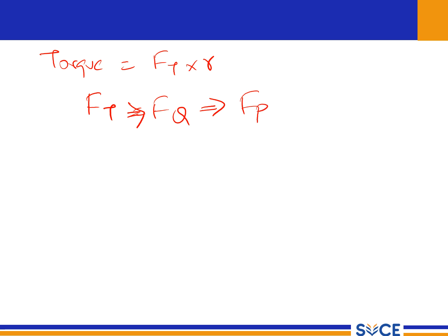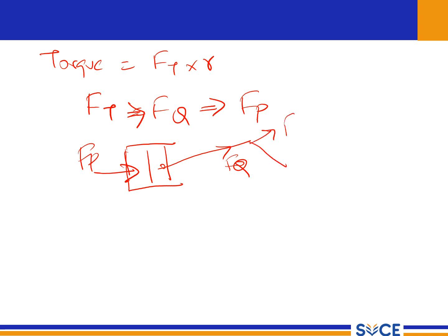That is the reverse order. The net piston effort Fp is transferred to the connecting rod, then to the crank. In order to calculate Fp, we need two forces, FL minus the inertia force. In the next step, we calculate the inertia force.